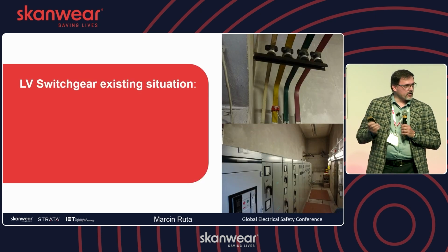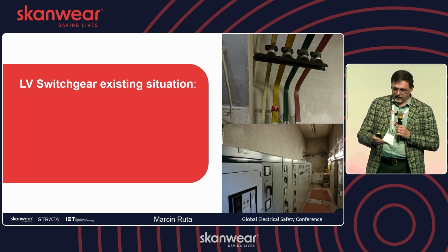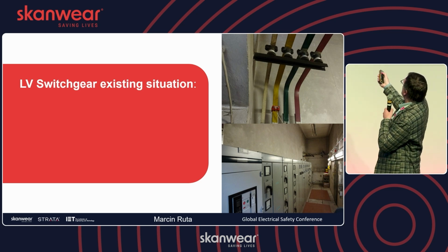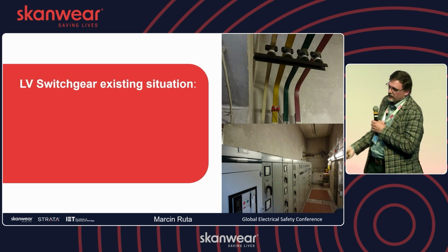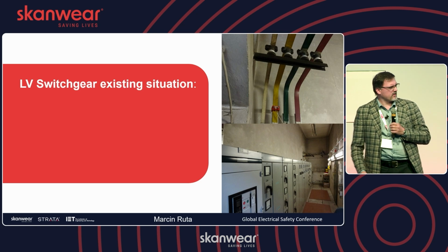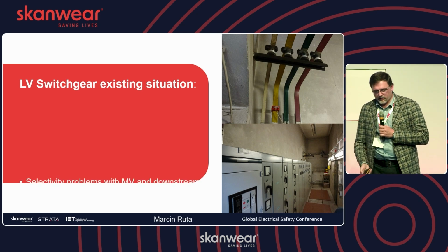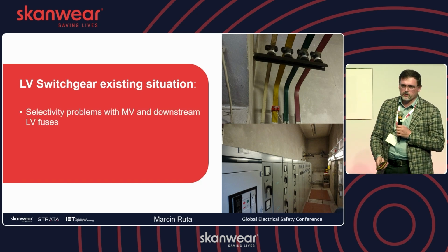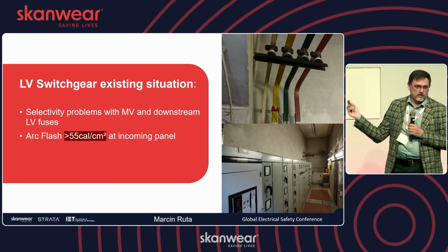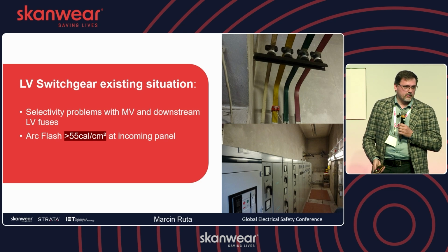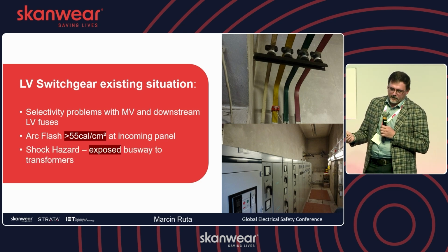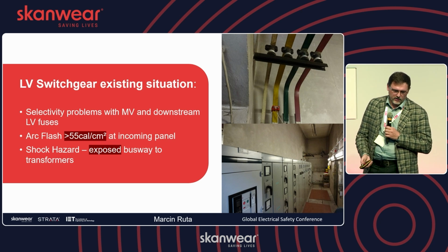What was the situation? I hope you can see it, but I will try to point it out. That was the real case on site. From when you enter, you actually can touch the main bus bar from the transformer, which is not a good thing. And also, we ended up having a lot of selectivity issues, a lot of protection problems. Arc flash energy at the main corner of the switchgear was actually above 55 calories per square centimeter, so quite a lot. And at the end, there were also some shock hazard issues.